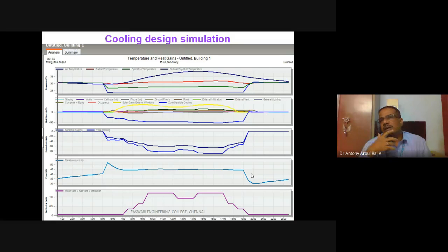So in early morning and night times you will have a lesser RH. You can see this in climatic data also. If you take the climatic data at night times, you find the RH coming down. During daytime, the RH will be increasing for a coastal climate like Chennai. I hope I have explained it. Is there anything else?